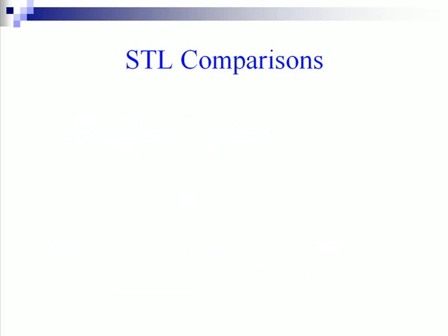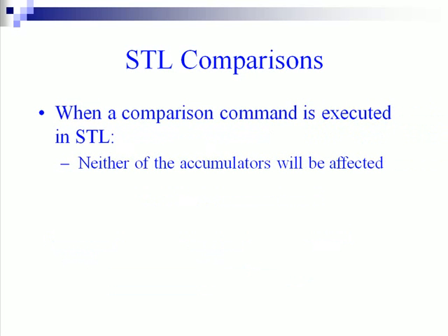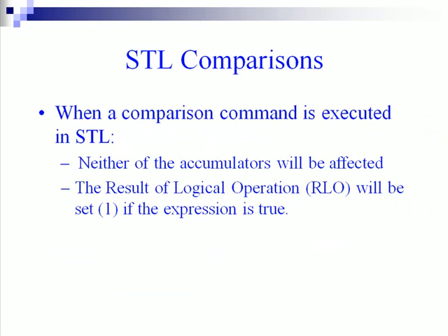When a comparison command is executed in STL, neither of the accumulators will be affected. However, the result of the logic operation, or RLO, will be set if the expression is true.